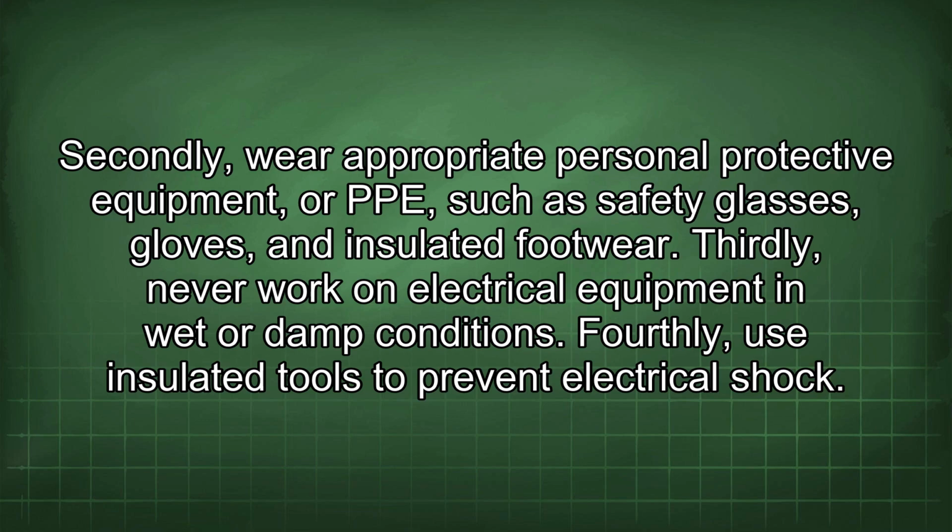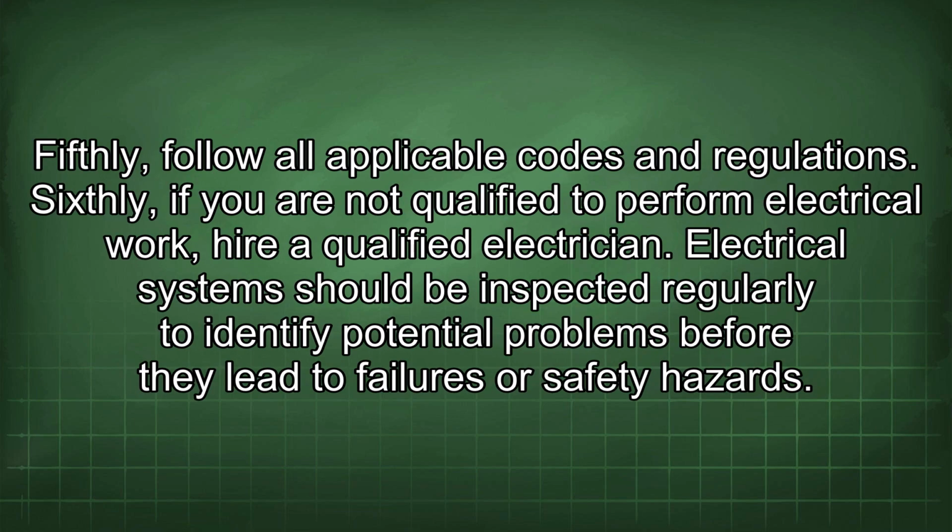Secondly, wear appropriate personal protective equipment, or PPE, such as safety glasses, gloves, and insulated footwear. Thirdly, never work on electrical equipment in wet or damp conditions. Fourthly, use insulated tools to prevent electrical shock. Fifthly, follow all applicable codes and regulations. Sixthly, if you are not qualified to perform electrical work, hire a qualified electrician.